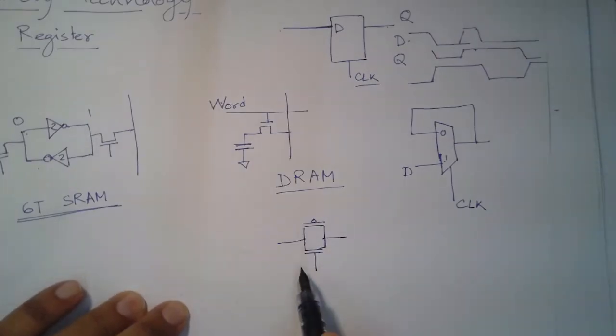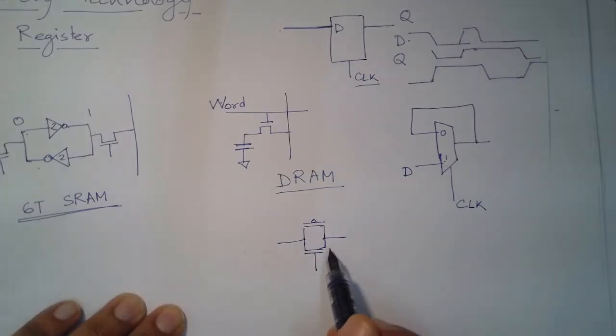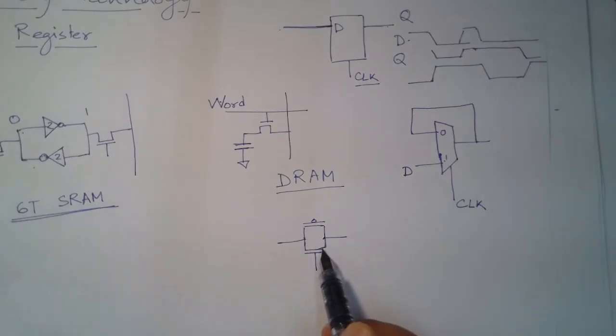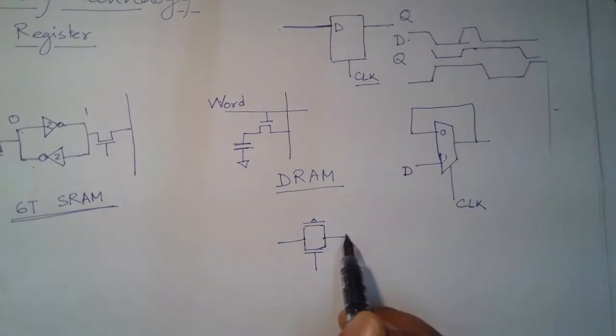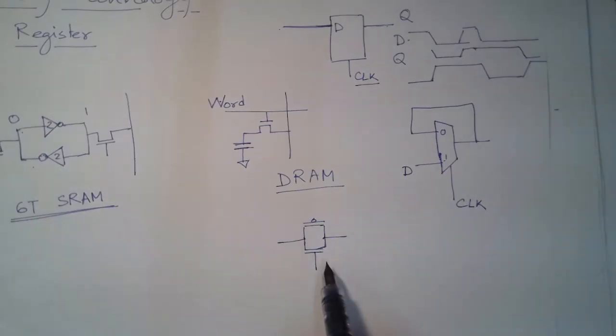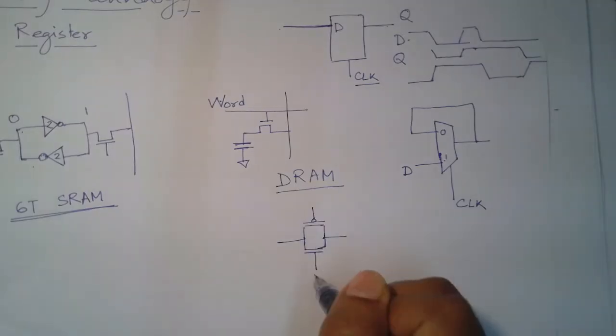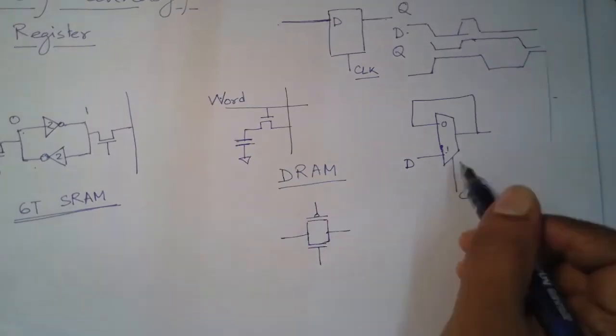The advantage is, why do you need a transmission gate, why can one transistor not do this? Because both PMOS and NMOS have their limitations. PMOS cannot transfer a very good low value, similarly NMOS cannot transfer a very good high value. So, since we want to transfer both high and low values appropriately, we connect two transistors in parallel, and the condition which switches them on is nothing but your clock signal.